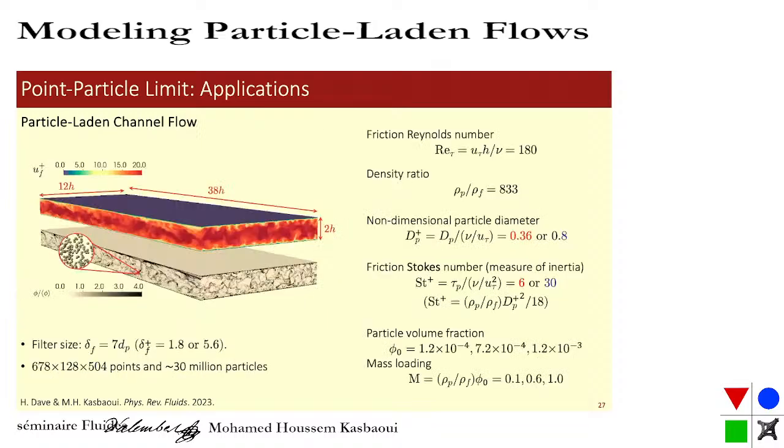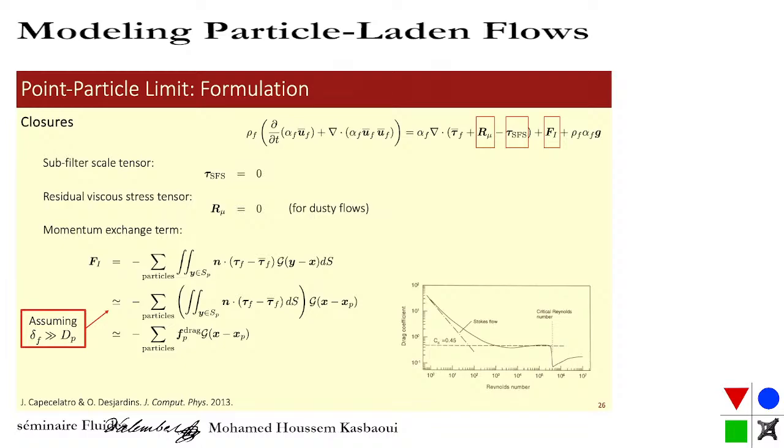Particle density, how does it come into play in your model? Yeah, really good question. So the particle density comes through, I think it's going to be in the drag force. It's going to be in the momentum exchange term here. This is going to be affected by the density ratio.